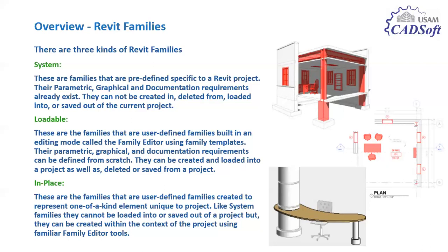Okay, and the last is in-place families. In-place families are again user-defined components, but they are restricted to the current project which you are working with. These are unique within the project. Some elements which you want to create, and which can be used only within this particular project, which I want to customize and create, are called in-place families.